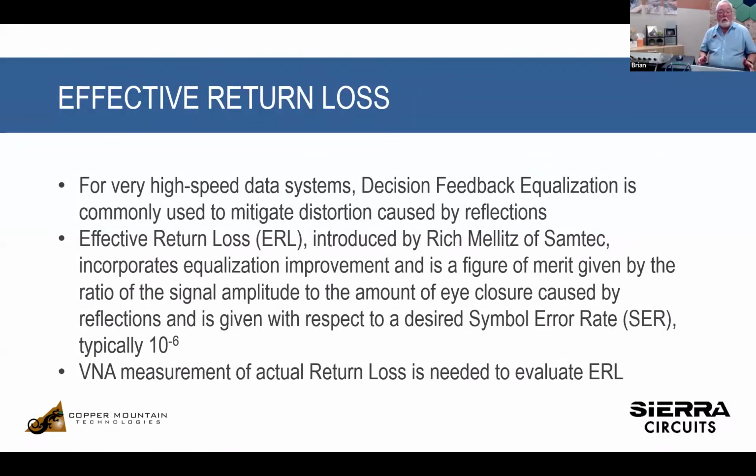I'll just mention here that effective return loss was introduced by Rich Mellitz of Samtec, and it incorporates the equalization improvement to give you a figure of merit for your digital design. But a VNA measurement of the actual return loss is needed to evaluate this.